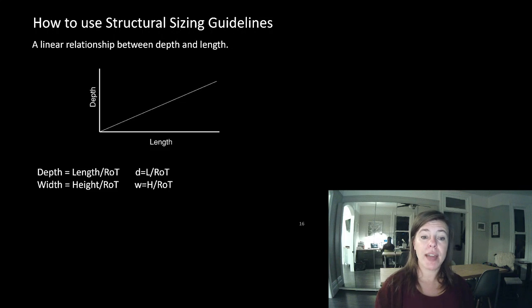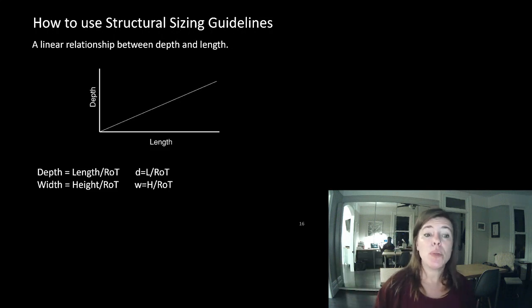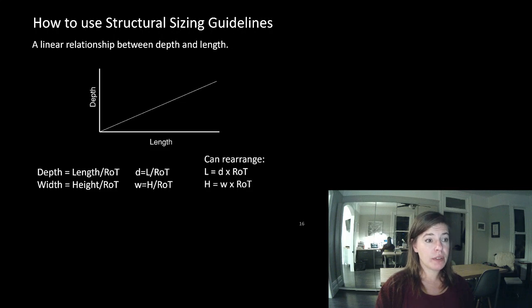So having a good idea of how deep your floor assembly is very early in the project is very important. Obviously, there will be elements, maybe you have one or two beams that are outside the range of normal, and maybe those can be dealt with locally, but it's not going to be the thing that shuts down a whole project from happening. And that is a thing I have seen happen in Toronto.